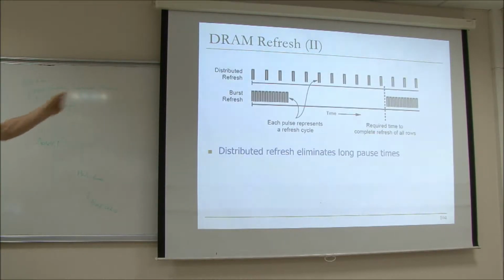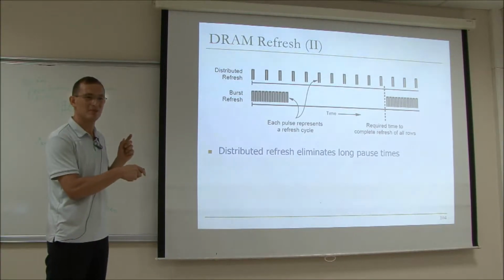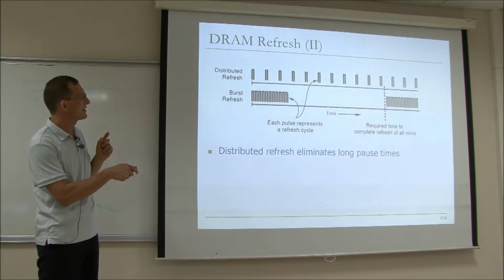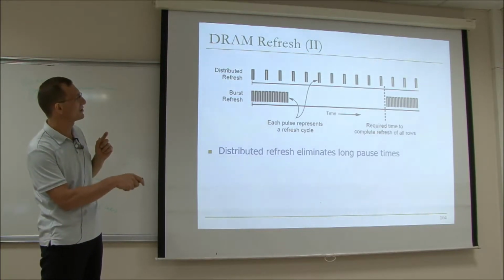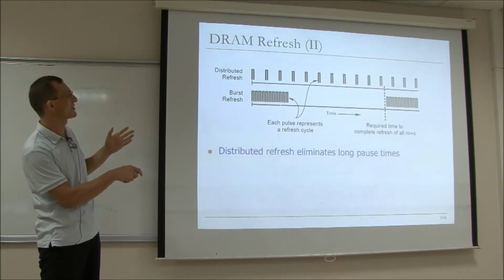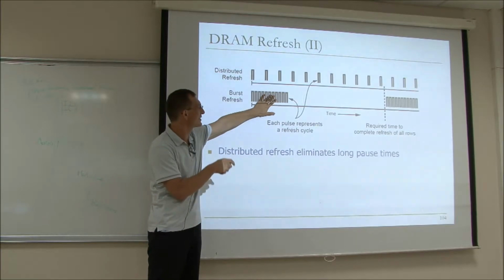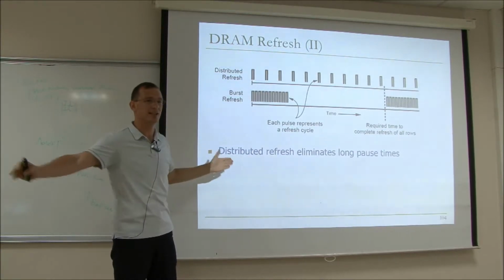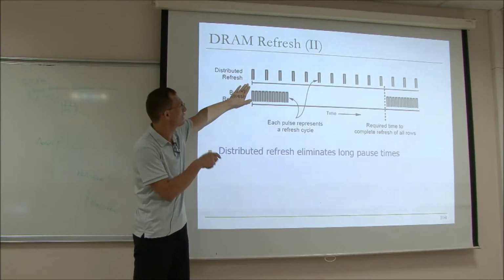And this is one example from one of Micron's data sheets. Basically, burst refresh looks like this. And if you actually don't have a lot of memory, you have these idle times where you're not refreshing. This is when you're actually refreshing and memory is not accessible, and this is when the memory is accessible. But many of today's systems actually interleave these refreshes of different rows, such that you get better quality of service impact.